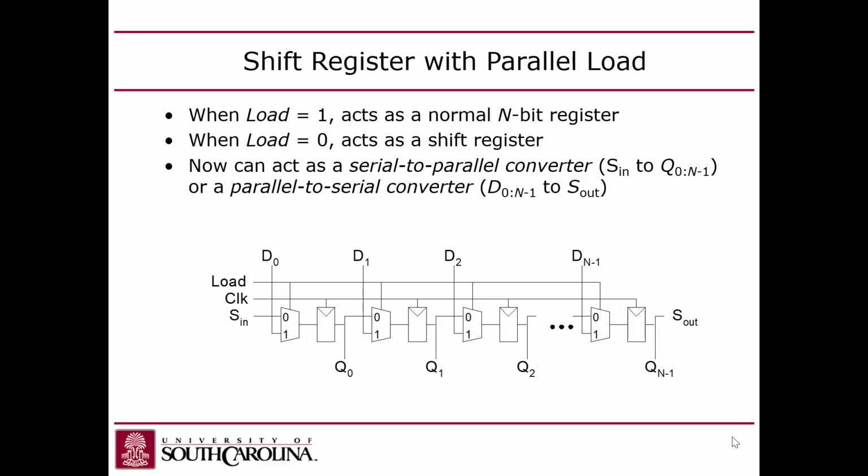If you set the muxes to 1, then instead of these D flip-flops shifting on the clock, they'll load on the clock, where you can provide a parallel load coming in to the one input on each of these muxes. Right? Now notice these Q outputs also allow you to do a parallel readout. So in this case, you can load it in parallel, you can read it in parallel, but you can also shift it out serially. Guys, does it make sense?